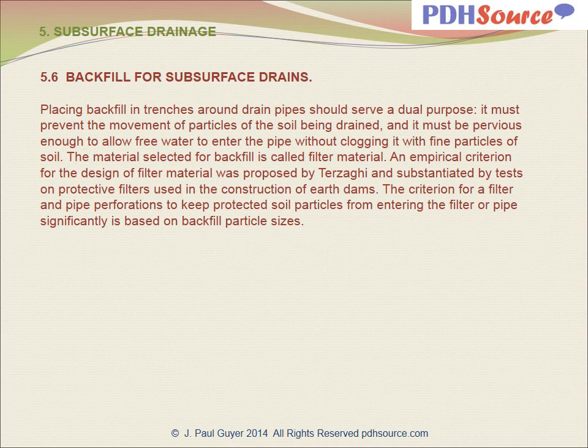An empirical criterion for the design of filter material was proposed by Terzaghi and substantiated by tests on protective filters used in the construction of earth dams. The criterion for a filter and pipe perforations to keep protected soil particles from entering the filter or pipe significantly is based on backfill particle sizes.